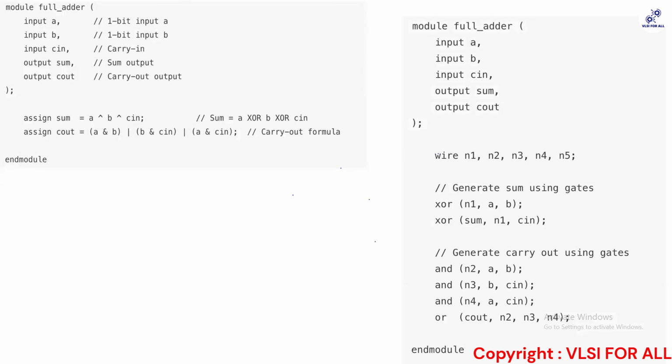But now, if you look into it, it has something called wires. Wires are nothing but the intermediate outputs. To explain simply, input and output will be transformed to ports in the real world, because this is the way you will provide the inputs. So there will be ports named A, B, and C, and some output ports named sum and cout. But inside, internal logic is working, and whatever outputs the internal logic produces will be shown in the form of wires.